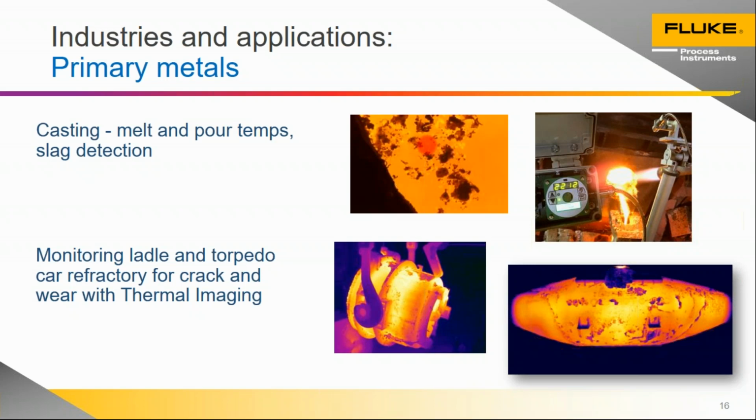Interestingly, this image is captured not by a camera, but by the pyrometer itself. Our endurance series pyrometers, the high temperature ones usually used for metals, actually have a video sighting capability. The intention there is for you to be able to aim at your process or sight as well as you can, even through remote means. But you can also monitor the process using that video feature. You can capture video onto the computer, you can capture still shots, and that's what I was able to do here. So it's a pretty clear picture when you have a nice bright and focused target to look at like that one.